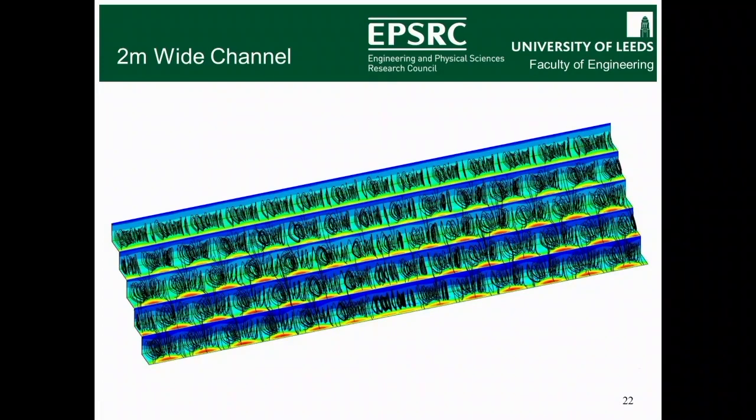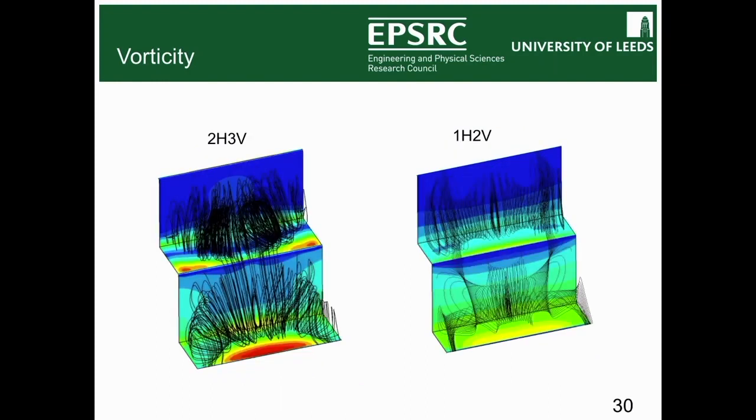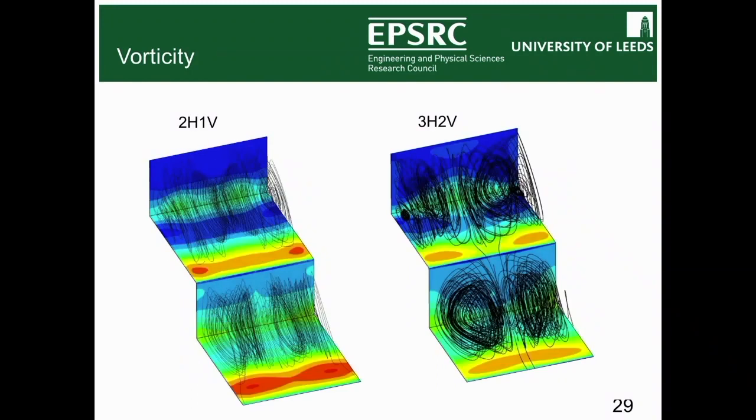Okay. Thanks. Just wondering what sets your pattern? Is it the geometry of the steps, and can you do something to try and excite something else? Yeah, well, I've looked at different slope angles, and when you get a much shallower angle or a much steeper angle, you don't seem to get it as much. But when you don't change the angle much, you still tend to see this pattern of vortices, though it's not quite as strong. But strangely, with the geometry that I've got, when you make it wider, you get the repeated pattern. When I change the angle with the same width I've got, you get the repeated pattern. But then if you make that wider, you don't. So I'm not really sure why.